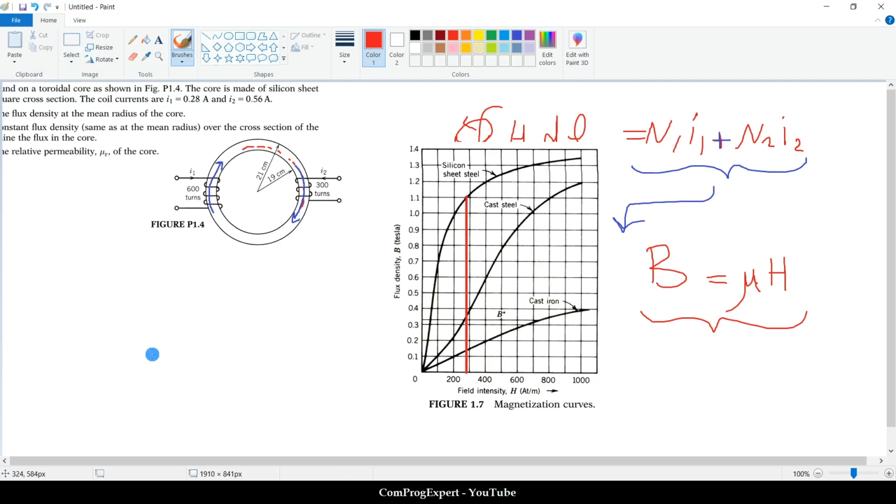Distance, when we have one line in ANSYS Maxwell, and actually we are going to plot this graph, B along this edge. Distance is this one. Here, distance is 0. And if we move in this direction, for this point, distance is equal to the segment length.